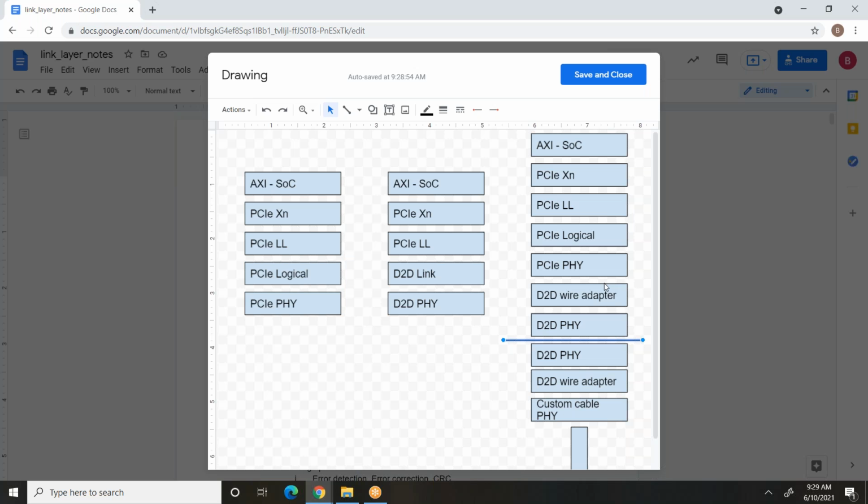Right. Yeah, that PHY is a high-power SerDes, so you don't want that. No, let's just say you want it for argument's sake. You're not trying to optimize anything. You're just trying to take a design that exists and use it as a bare die. And the other guy is a die-to-die PHY, so you essentially need a wire adapter. If this has 64 wires, you take these 16 wires and spray the bits across these 64 wires. Okay.